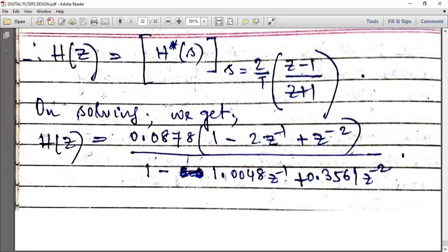Means you cannot change the type of filters much if you use windows. Flexibility is lost. And the third point is sometimes it is difficult to determine the type of window in advance, as also the duration M, what is it? It is the length of the FIR filter to meet given prescribed frequency specifications. Okay. So these all are the advantages and disadvantages of using windows.